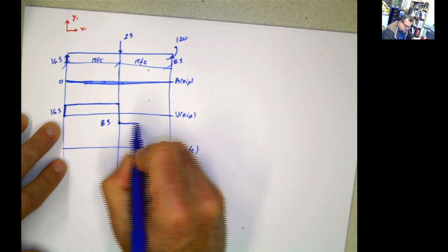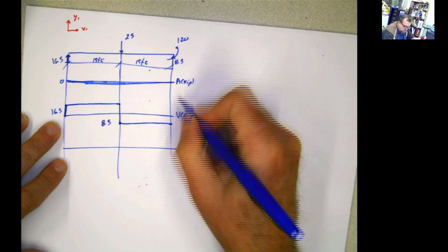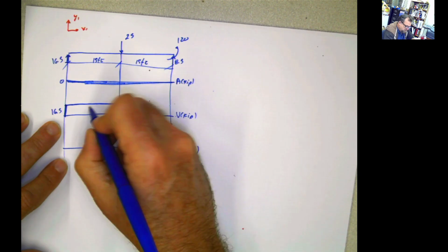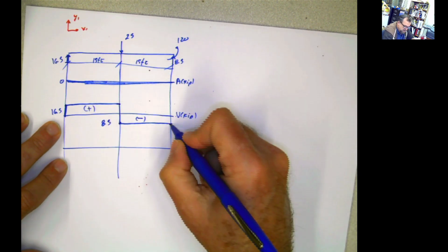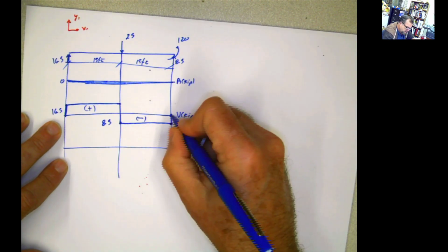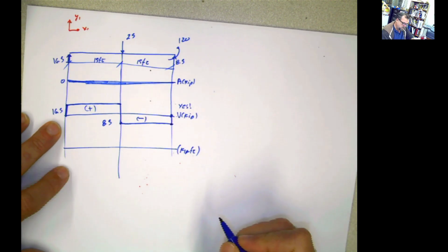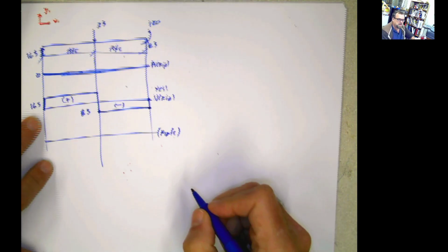Constant again because there's not any load up to here. Constant here, go to this point, negative 8.5, positive 8.5. I find this point here, force of 8.5 pushing it up, reaches 0, and you do yes. This is good. It closes in 0, so that part is correct.